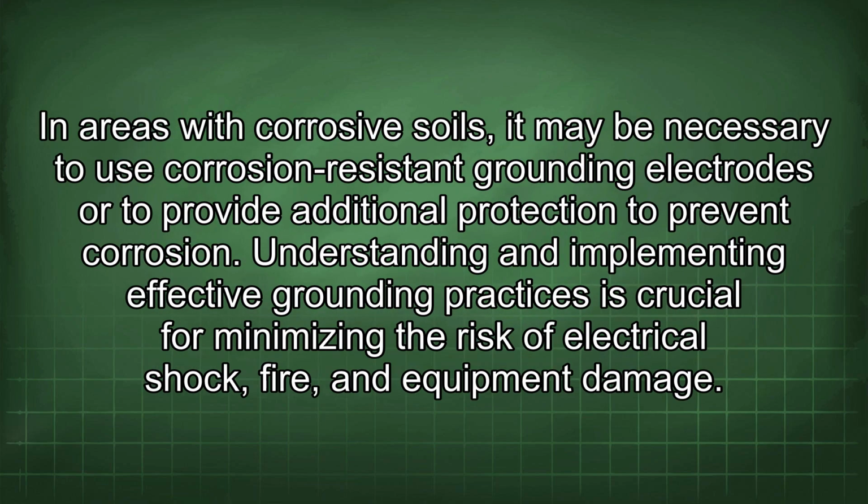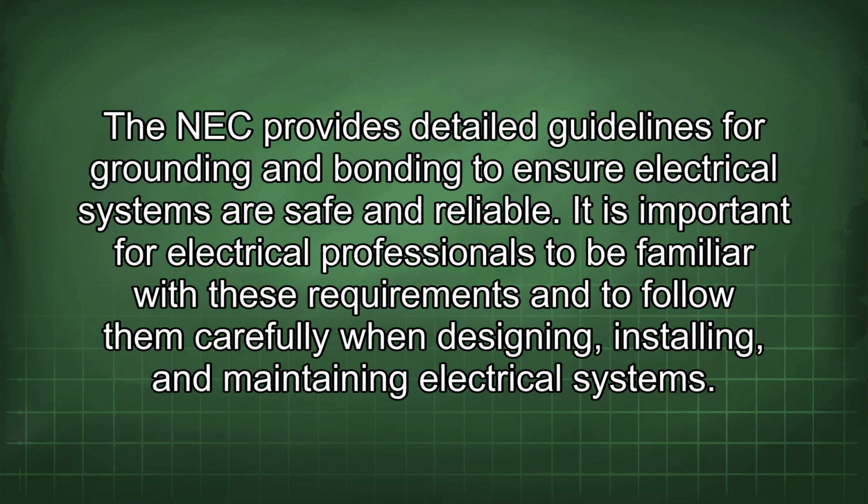In areas with corrosive soils, it may be necessary to use corrosion-resistant grounding electrodes or to provide additional protection to prevent corrosion. Understanding and implementing effective grounding practices is crucial for minimizing the risk of electrical shock, fire, and equipment damage. The NEC provides detailed guidelines for grounding and bonding to ensure electrical systems are safe and reliable. It is important for electrical professionals to be familiar with these requirements and to follow them carefully when designing, installing,